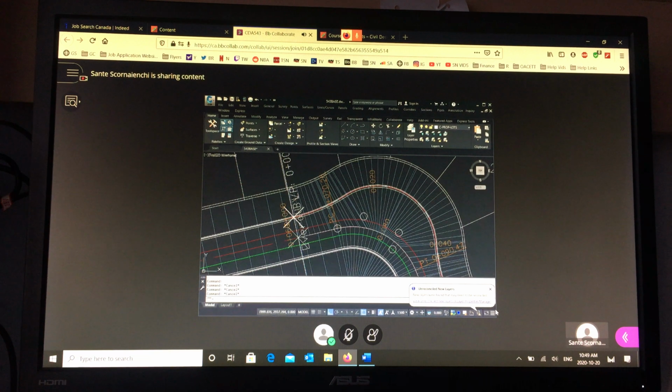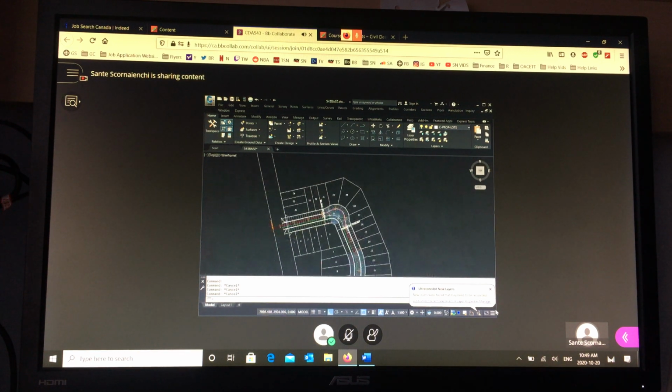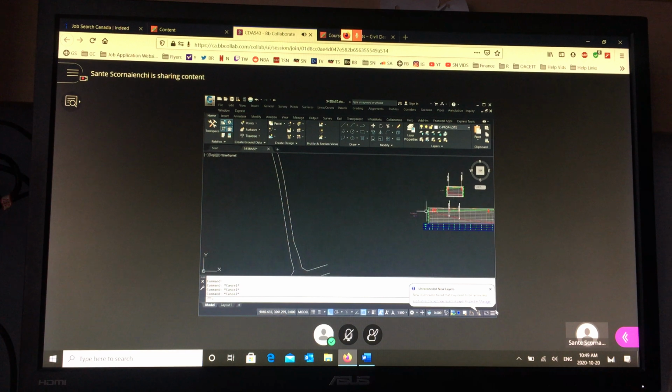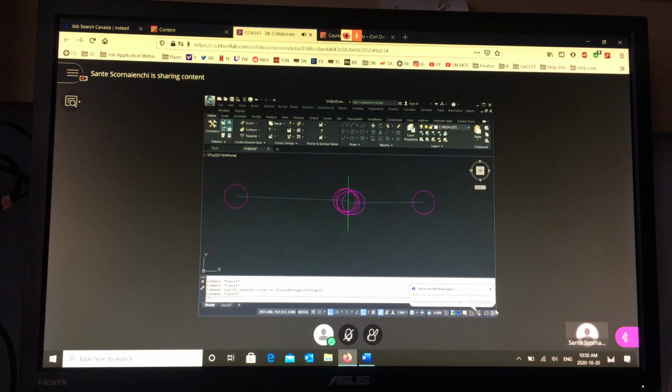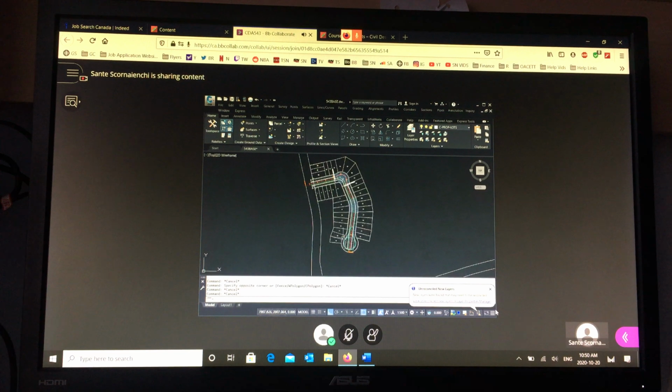So in the direction of increasing chainage along the gutter, the left side has the boulevard, the right side has the pavement. Okay, that's the orientation of the alignment, and that's why I created my subassembly to look like this, right? There's my gutter. I have the boulevard on this side and the pavement on this side. I want to reuse this. I don't want to have to recreate another one, so I'm going to be mindful when I create my alignment here.